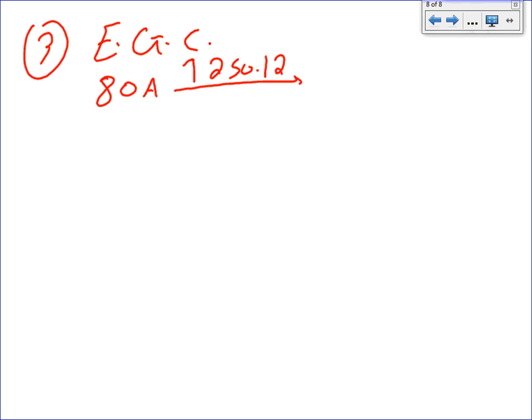Table 250.122. Number 8. One conductor, number 8. Now here's a question for you. If this calculation ends up with number 1 out, and the phase conductors we sized at number 8, you don't have to go that high.